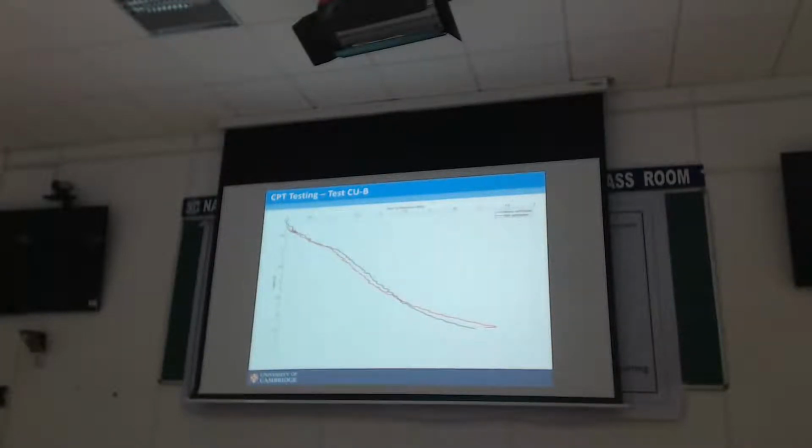Now, they're reasonably consistent. The slope is only 4 meters deep, but we can't go all the way to the base. Mostly because we're scared we'll drive our CPT into the base, in which case we'll destroy it. So we stop about half a meter in terms of prototype scale of the base.